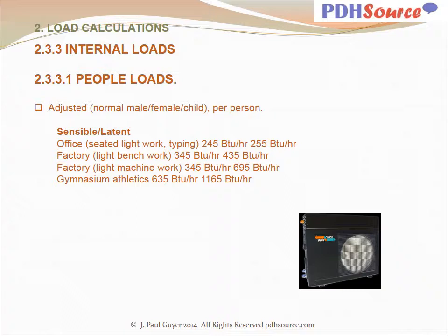And so that hot human body is heating up the interior of the building. And how much is it heating it up? Here are some rule of thumb figures. In an office environment, office workers would be providing about 245 BTUs per hour of heating.